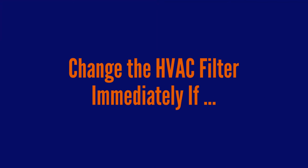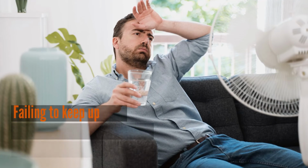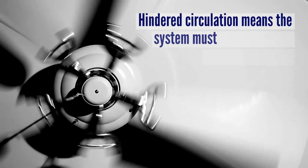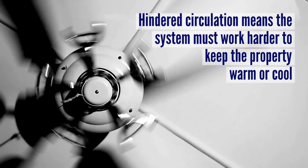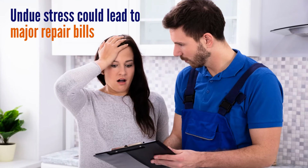That said, it is important to change the HVAC filter immediately if you inspect it and find that the filter is damaged in any way, or if the filter is damp, which could quickly grow mold and circulate harmful spores throughout your home's air. Failing to keep up with simple HVAC maintenance can have costly consequences, including the risk of unit failure or emergency repair. Any hindered circulation means that the system must work harder to keep the property warm or cool. Therefore, the system experiences undue stress, which could lead to major repair bills.